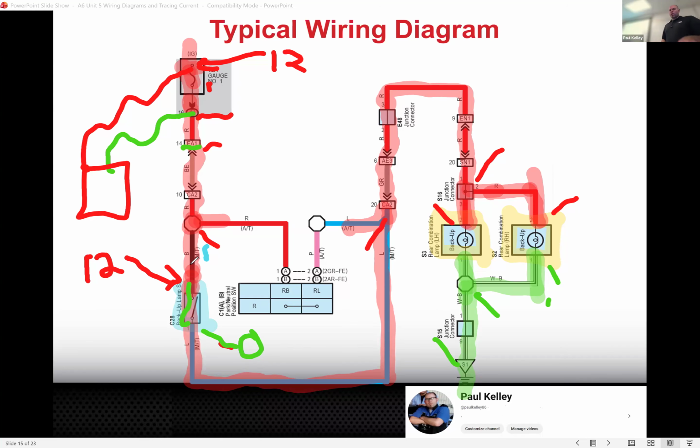But if you measured 12 and 0, you know the switch is bad. You verified that it's in reverse, but you know the switch is the problem. So when you call them and you tell them it's going to be this, this, and this price, and then they okay it, and they're like, yeah, go ahead and fix it. It's going to be $100 for diag, $100 for replacement, and the switch is $25. You're looking at $225. That's why the bill is what it is.